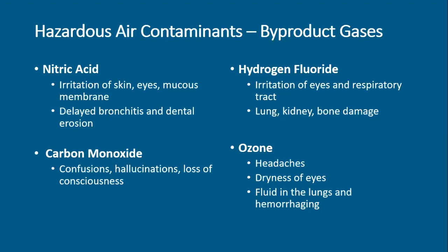Ozone can result from the ionization of the air surrounding an arc or high voltage. Exposures to ozone can cause headaches, coughing, shortness of breath, or fluid in the lungs. Prolonged or elevated exposures to ozone can intensify symptoms, and chronic exposures may lead to asthma.